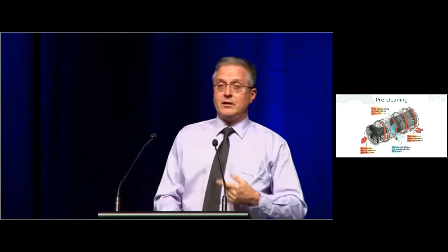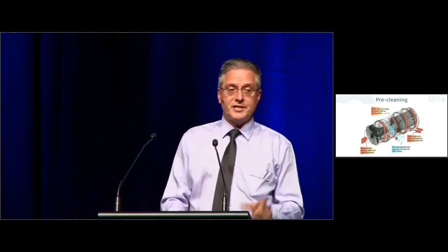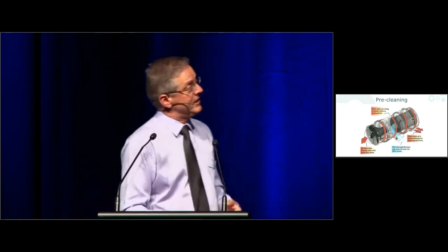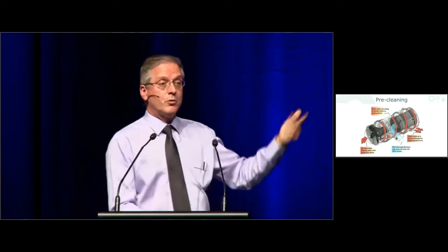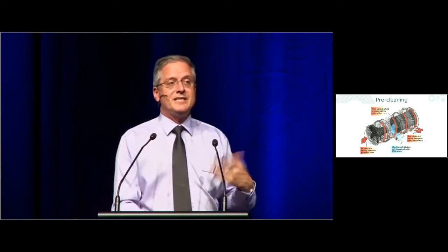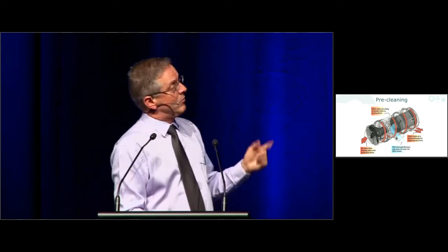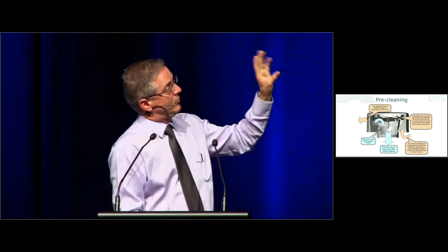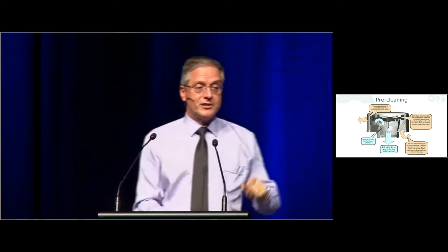There's a couple of organisations or providers that will retrofit good quality filtration systems to existing cabins, to plant. And both of them have what's called a pre-cleaner, and that's like your scrubber from earlier on. So a pre-cleaner that just basically spins out the oversized material and stops your intake filtration from being clogged up as quickly as it would otherwise. So that's one type. This one you can see is a second type with a propeller or a fan at the top that spins out the oversized dust.